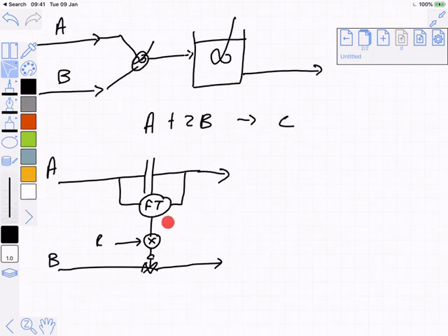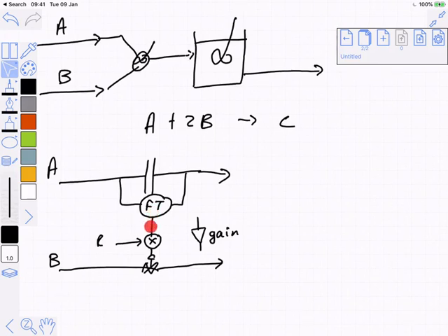But I think the most important thing that you have to understand is, even if you ignore all the mechanics, even if you ignore how exactly the flow is being measured and how exactly the valve works and all of that stuff, it should be obvious to everybody that the units conceptually of a flow are not commensurate with anything that I can imagine actually sending to a valve.